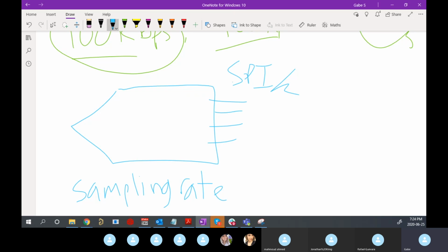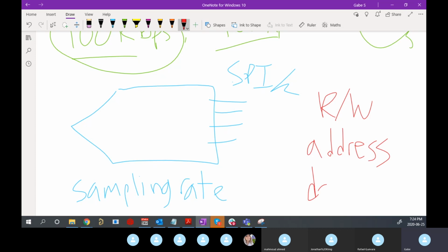But to be fair, with I2C, all of that is built into your hardware, right? All you have to do on the VCU side is basically set if you're going to read or write, set the address you're going to send, and then set whatever data you're going to send, right? If you're going to read from a register or write data to a register, those are the only 3 things you have to do. So it's pretty good. And we use it for that current sensor because that's what the built-in protocol is for that.